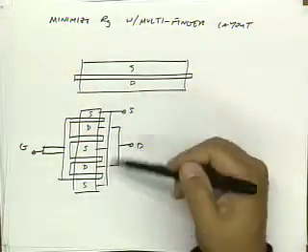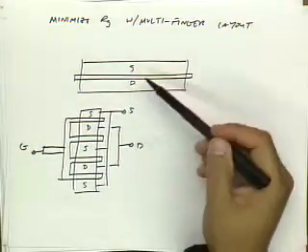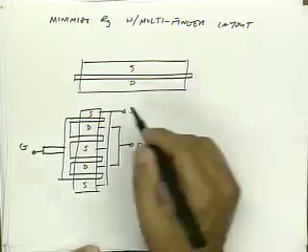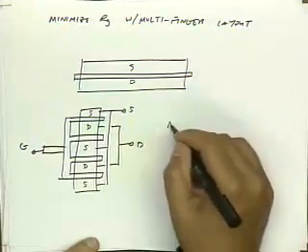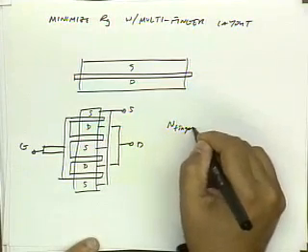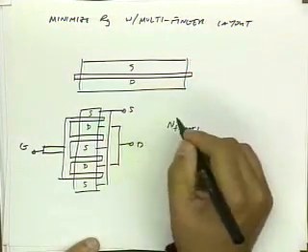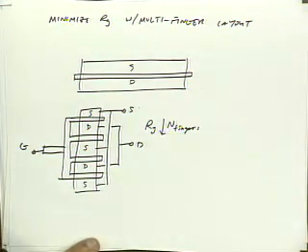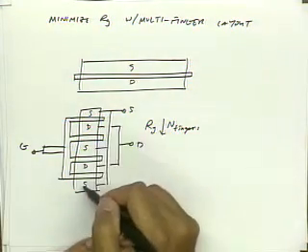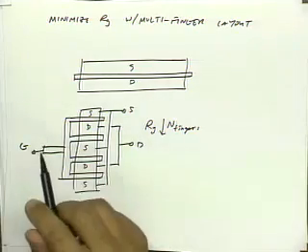And you can see this has a twofold improvement, because not only am I reducing my gate length by n, so if I have n fingers, so our gate resistance goes down proportional to the number of fingers, but since these are now in parallel, I get another factor improvement.